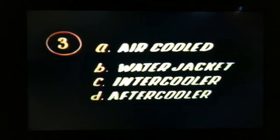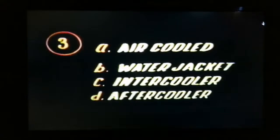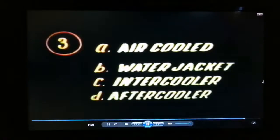For question number 3, the 4 methods are air-cooled. This is the method used with small compressors. Water jacket. This method circulates water around the cylinder to absorb some of the heat of compression. The intercooler removes heat from the air between stages. And finally, the aftercooler, where heat is removed again precisely the same way as in an intercooler.